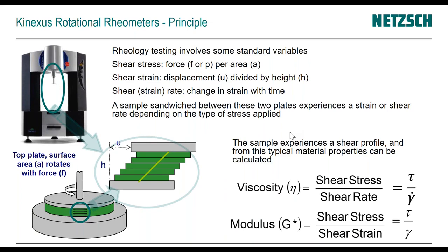The next aspect I want to talk about is rheology, because I find it a very, very powerful tool to study recycling and behavior of recycled material, as well as intentional and unintentional blends. And the typical way to study these effects would be at lower shear rates. So we would use a rotational rheometer, in that case, one of our Kinexus rotational rheometers.